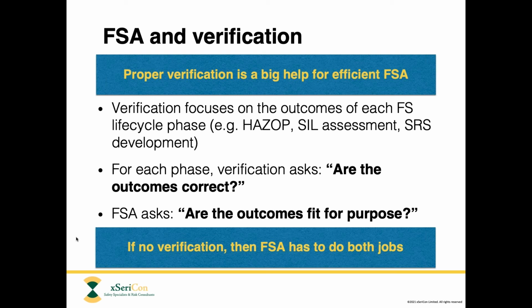So just to clarify one more time, what's the difference between verification and FSA? Well, verification is focusing on the fine details that are expecting to come out of each life cycle phase, such as HAZOP or SIL assessment. And it asks the question, given the inputs and given the procedure, did we end up with the correct outcomes from that phase?